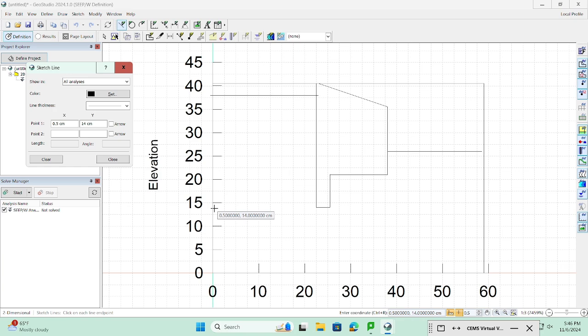For the soil level, if you can remember, guys, the soil was about 4 to 5 centimeters below your downstream water level. So I'm going to assume in this case that the soil height was 22 centimeters from the bottom, from the datum. Okay, so your datum is here, and your downstream is at 26. I'm going to make the soil level be at 22.